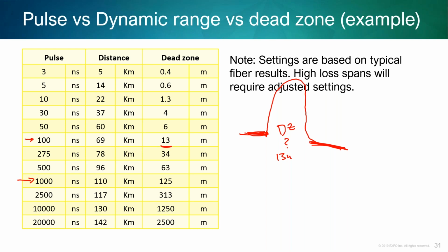Kevin? Right? Yes. We have another question. Sure, that's fine. Does it make a difference if the circuit is live? It does, in that you cannot use 1310 and 1550 on live fiber, because it'll interrupt traffic. I mean, obviously, you're already intrusive into traffic anyways, mostly. But it won't work because the incoming light can damage the OTDR. On most OTDRs, right around negative 26, 25 dBm, you can damage the detector, which is not a whole ton of light. You need to use what we call an in-service OTDR.